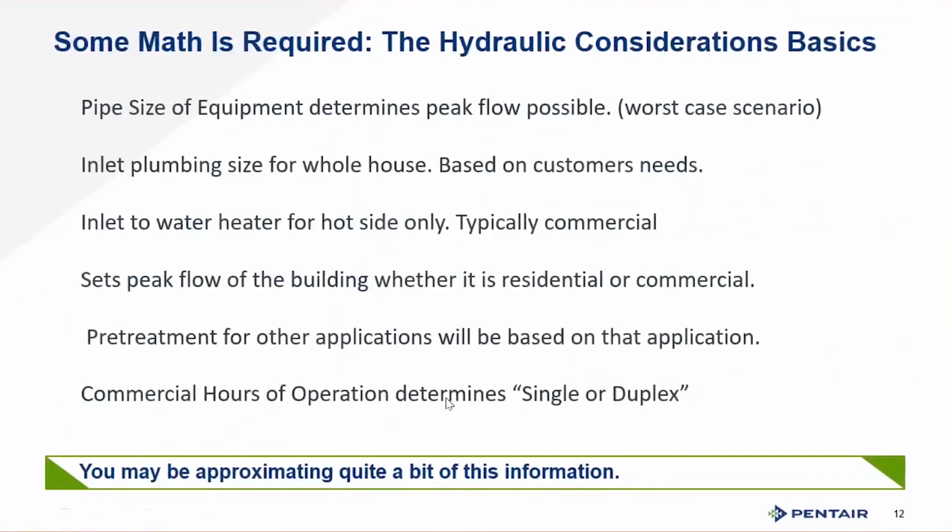Now we're talking about the hydraulics of the situation, the installation envelope we're putting our softener in, the system we're putting in. We understand how much resin is required. We're starting to understand the impact of flow on that. So what happens when we're outside the flow restraints of our resin? What are we going to have to do?